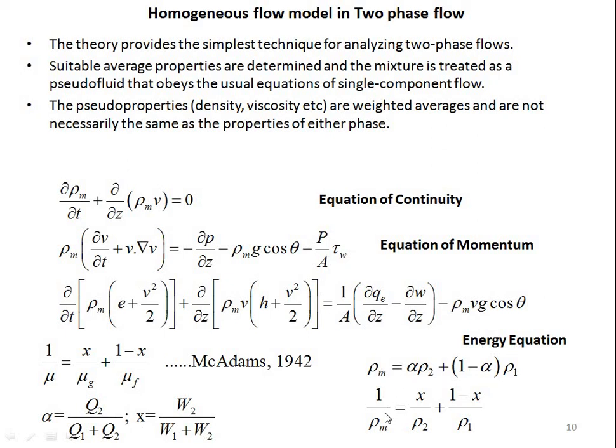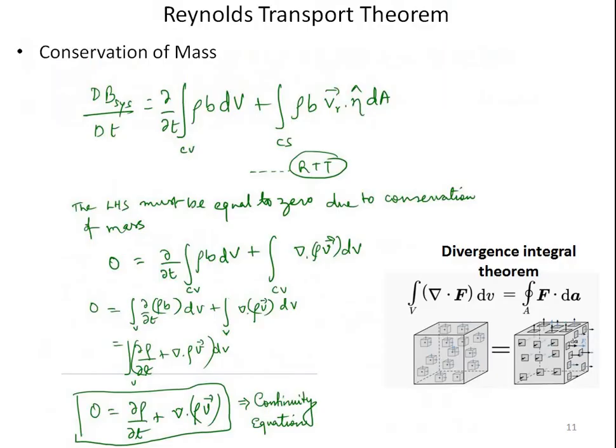In a similar manner, the equations of continuity, momentum, and energy can be derived with the help of the Reynolds Transport Theorem, which we are coming to in subsequent slides. That will be discussed. Now we come to the Reynolds Transport Theorem. It basically relates our Lagrangian part, the LHS dV system by dt, which is a substantial time derivative, with the Eulerian part. This is our Eulerian part, the control volume, and this is the net efflux of velocity or any property which is coming in and exiting out of the system.